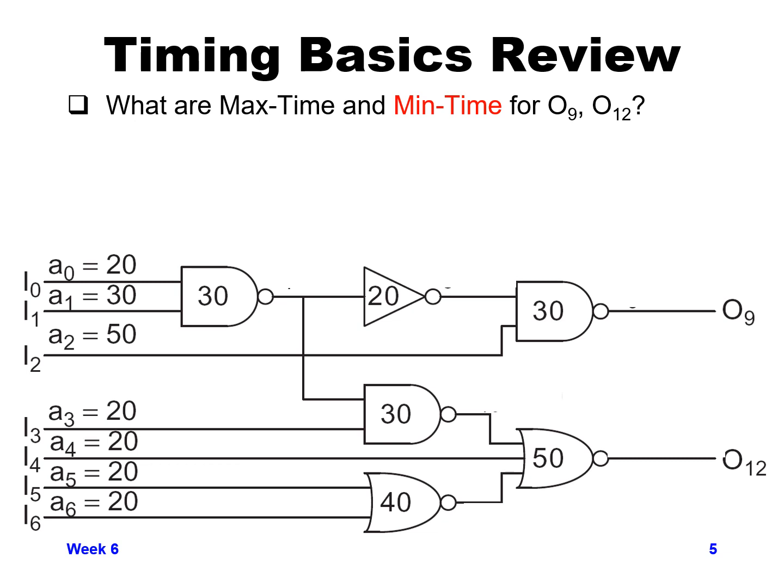So the NAND gate in the upper left is 30 picoseconds from its input crossing 50% to its output crossing 50%. The inverter, kind of in the middle upper, is 20 picoseconds delay from the input to output switching, etc.